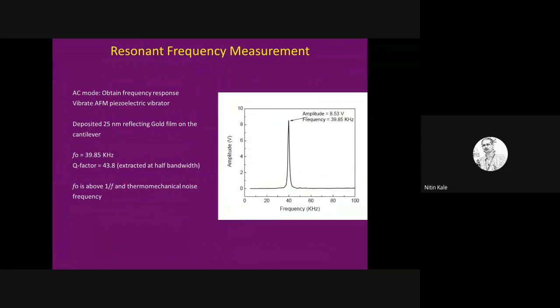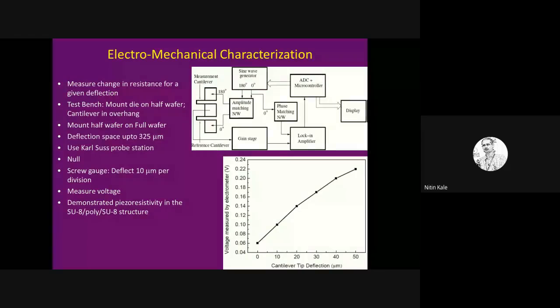Then the cantilever that we had fabricated can also be put in the nose holder of the atomic force microscope and vibrated. Then you can find out its resonant frequency. So those measurements were done. In fact, we found the resonant frequency to be about 40 kilohertz. Then the final piezoresistance demonstration.